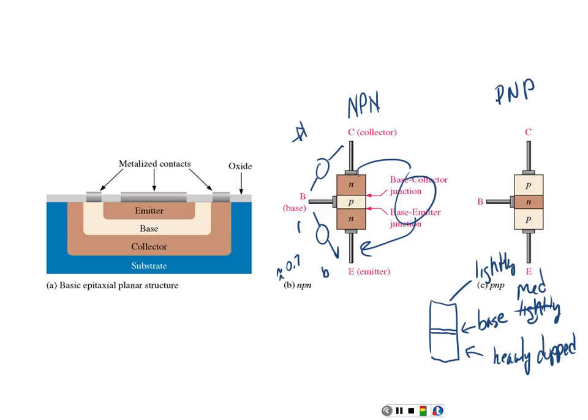Well, show me two p-n junctions that I'm forward biasing. So my red lead would be on an N, which is pulling it that way, right? My black lead would be on the E, which is pulling it that way, and sandwiched in between, I got a P that's not doing anything, right? So when we measure collector to emitter, we should measure extremely high ohms, extremely high in both directions. And this is the way we check a transistor with an ohm meter, just like we do a diode.